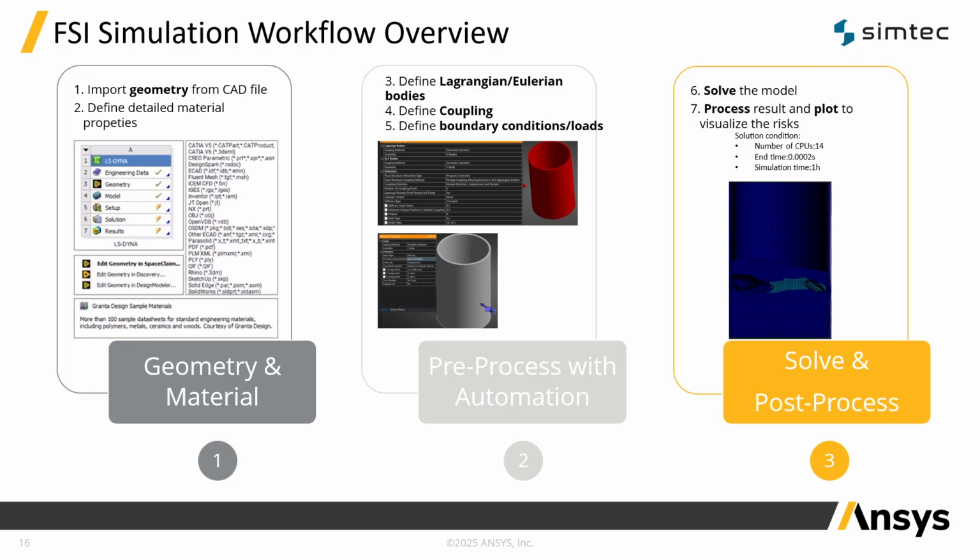LS-Dyna is known to have several material cards available, both in LS-PrePost and also in Ansys Workbench LS-Dyna. There, we must consider very carefully the properties of the fluid and the properties of the solid. Keep in mind that we want to see the deformation of the solid, so we must include different types of failure criteria from the variety that we have to choose from, and also include the correct properties of the fluid. After that comes the preprocess.